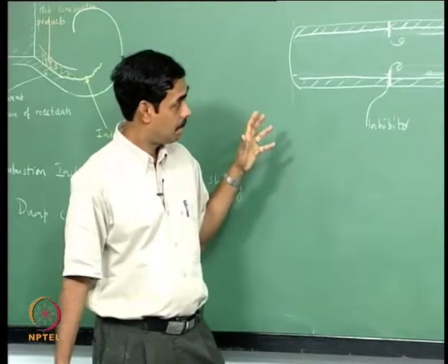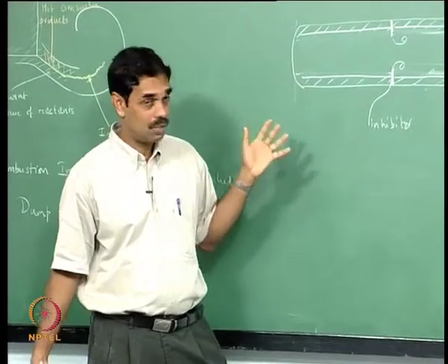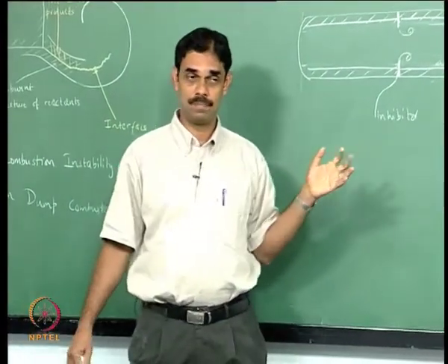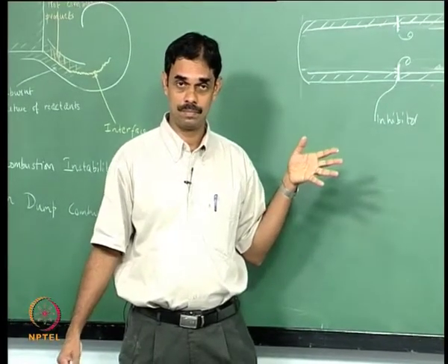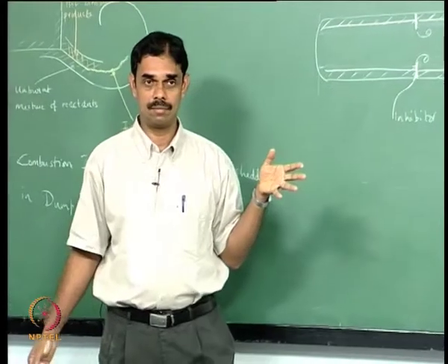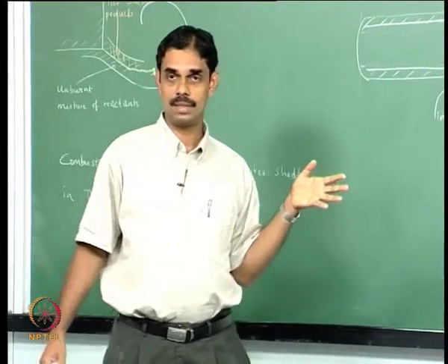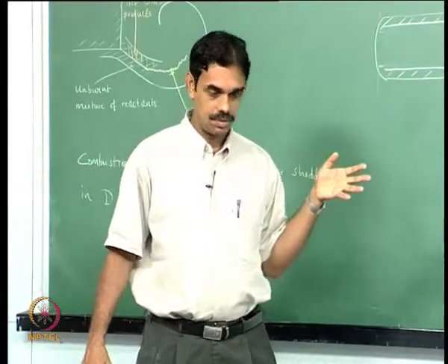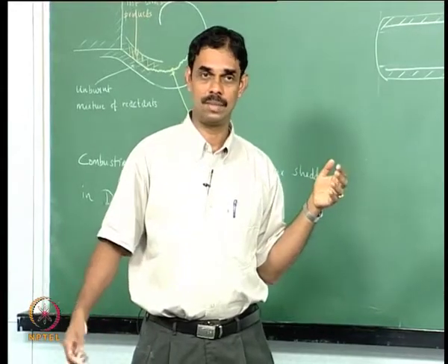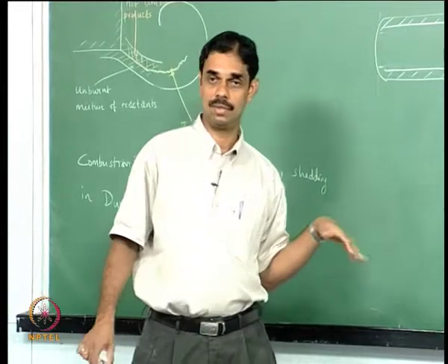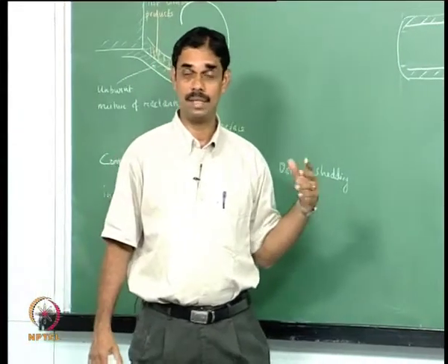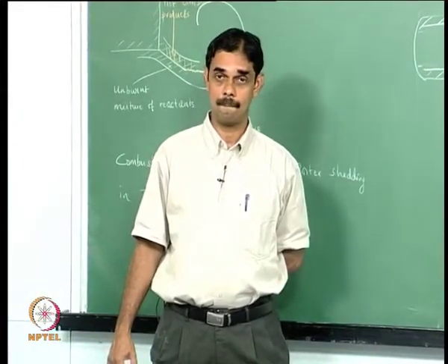So in this case, even if you do not have any combustion, just the aerodynamic instability itself may be sufficient to cause some problem. We have to check if, I think we can probably tolerate 0.1% of pressure oscillations or 1% of thrust oscillations. If they are below that, then the motor is okay, but anything more, I think the motor would be unsafe.